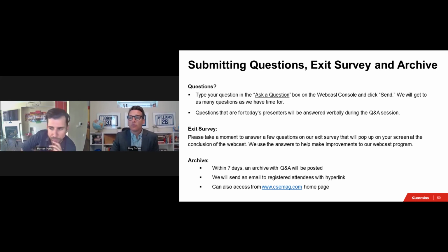Perfect. What are the best strategies to ensure the health and readiness of an ATS? Great question. You obviously want to do monthly testing, right? It's required by code for certain applications. Refer to the manufacturer's recommendations for testing and inspection.